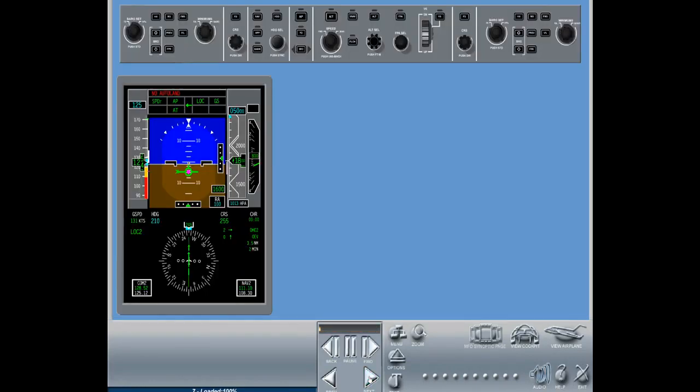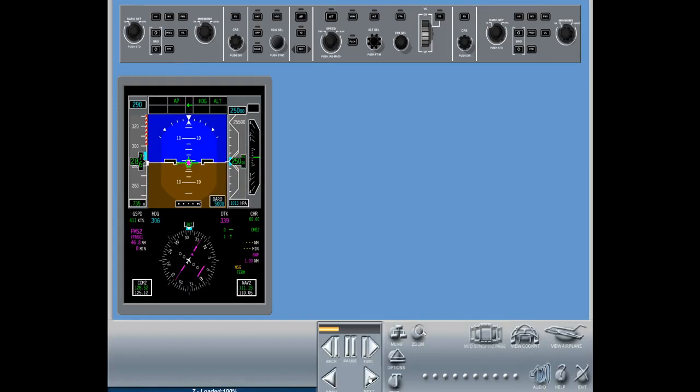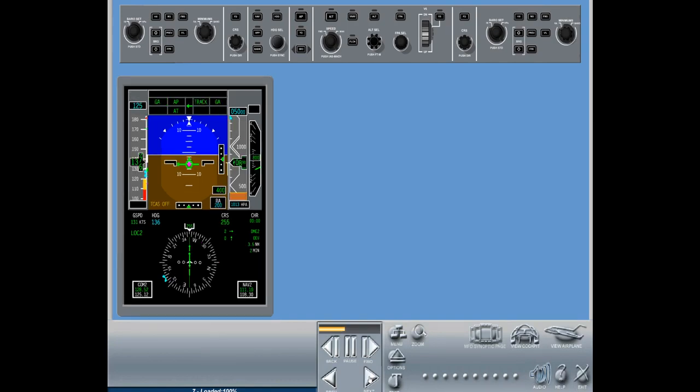If engaged, loss of the Autoland mode results in the monitor warning posting a red No Autoland warning in the third line of the FMA and triggers a No Autoland aural warning. The monitor warning function cancels the visual and aural warnings when the autopilot disconnects or the flight director go-around mode is set.